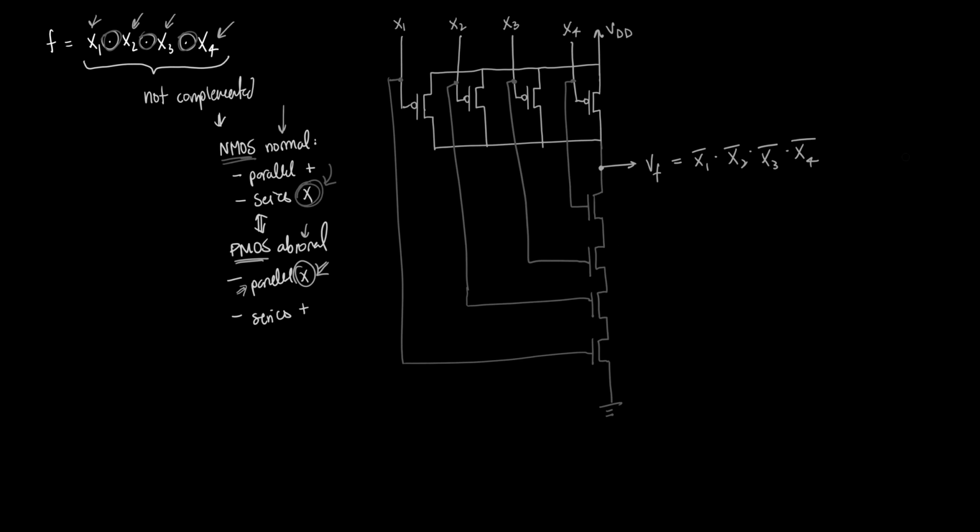And that's because by default, if we just took the raw output of this, it's going to release the complemented version of our function f. So in order to fix this and correctly represent our function f with none of the inputs complemented, what we need to do is run it through an extra inverter, just like we did last time. So what we're going to do is connect this inverted output that's on this wire to an inverter.